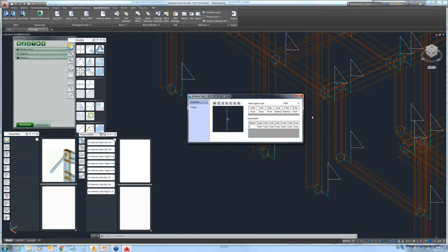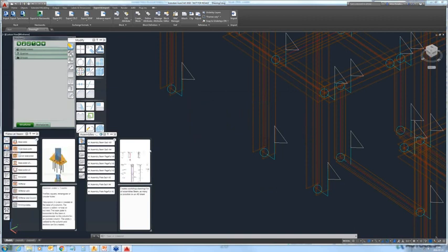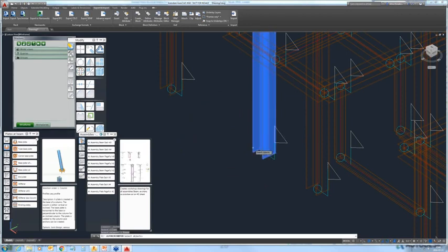It's pinned because all the rotations are free, and you can also see the results, I mean the forces, the reactions that were imported. And now if the design of the steel connection is the responsibility of the fabricator, he or she may use the connection module in Advanced Steel, for example, to create a pinned connection at the bottom of a column.